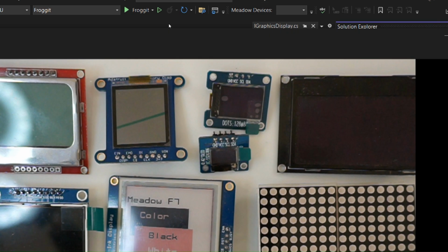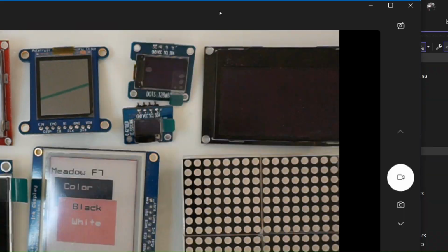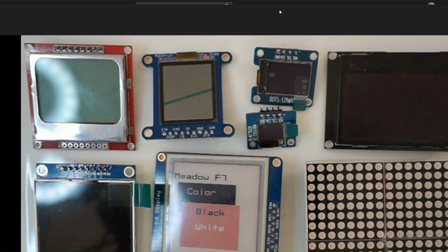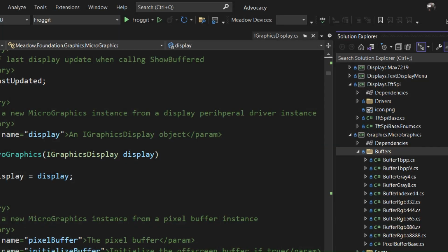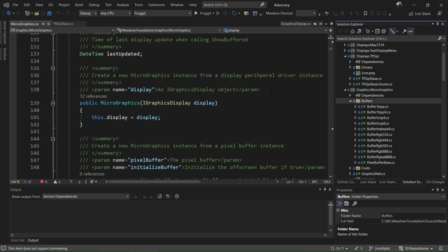And let me even grab that back over here. So that buffer would be used for things like our Nokia display here, or these ones in the middle here, these are actually OLED single color displays. So this is one on the right hand side here. So we've got an optimized buffer, integer precision, and these all have really interesting properties. Again, there's other abstractions, so they can take in a color object and convert that color to a color representation that makes sense for that display.